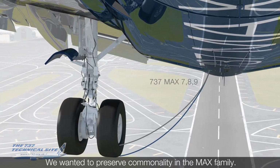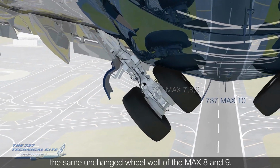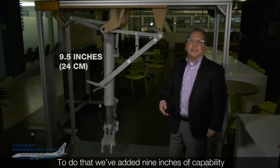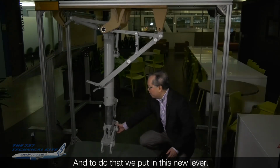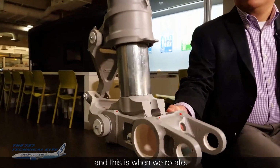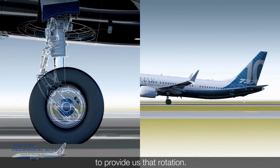So let's hear from Gary Hamatani demonstrating and describing the Max 10 landing gear in person. We wanted to preserve commonality in the Max family. We needed to get the landing gear back into the same unchanged wheel well of the Max 8 and 9. To do that, we've added 9 inches of capability to the gear lengthwise when the airplane rotates. And to do that, we put in this new lever. So this is really the key. This is on the ground, and this is when we rotate. And this lever extends down that 9.5 inches to provide us that rotation.